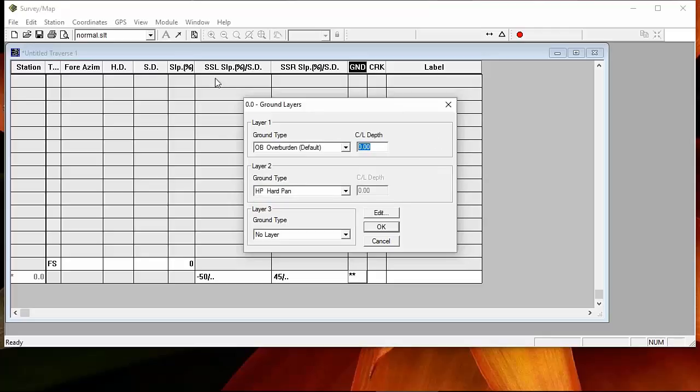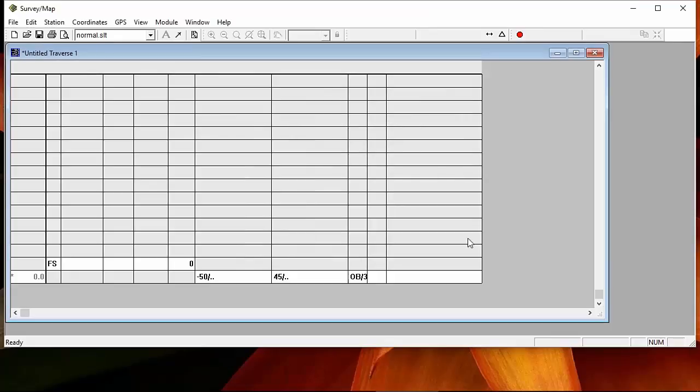I can't remember whether I've started by default in feet or meters here, but the example I'll be looking at later will be in feet. Right, 4-shot, azimuth, let's say we're going north, so I'll go a little east of north. Distance, how about 56 feet? And now it's prompting me for a vertical direction, a slope. I'll put in a % slope here. And now we're on to the next shot.